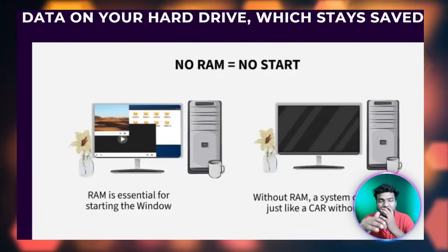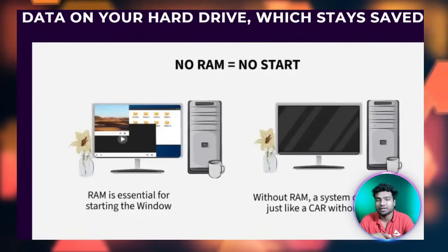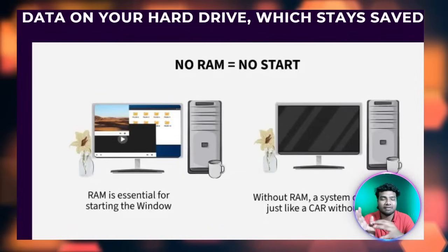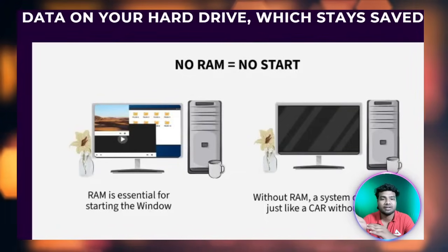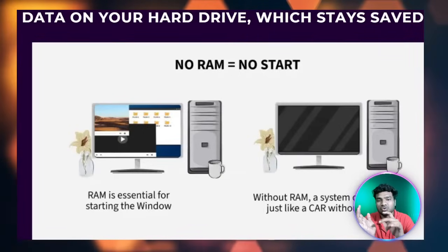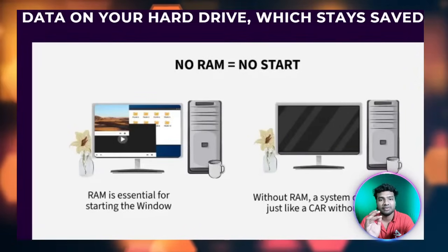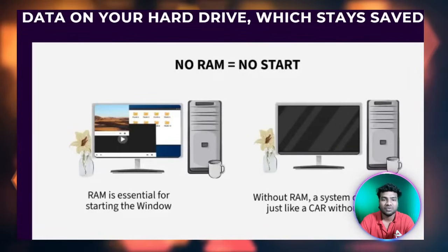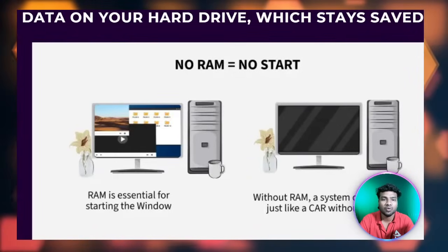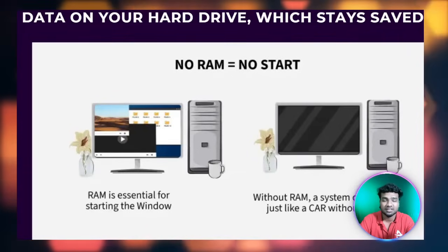EEPROM means electrically erasable, programmable, read-only memory. So we have the boot instructions in the EEPROM, in the read-only non-volatile memory. But how is it executed? To execute this, it needs one input signal from the device. That signal is clock pulses. When the BIOS receives one clock cycle from the crystal, it will execute the first instruction.